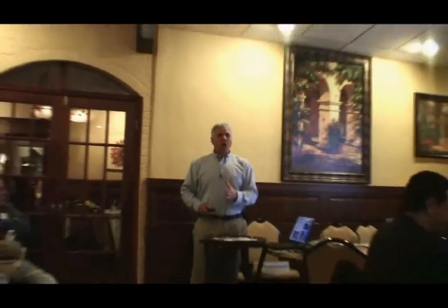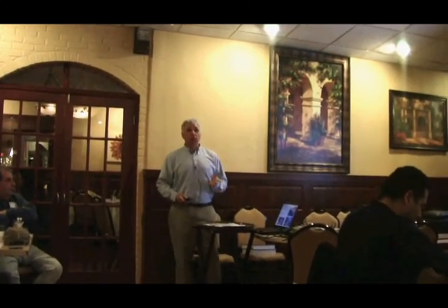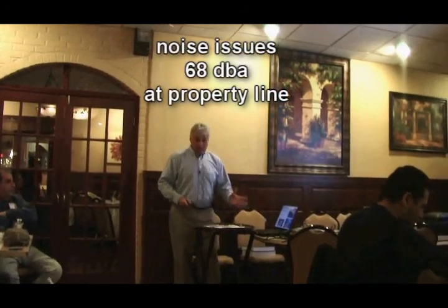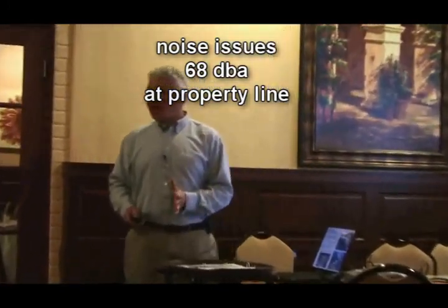Yes? Anything like a property line, like the fence? When I say there's a fence, do you have to be a certain distance from the fence or anything like that? The code right now, the village code, is property line, not fence. But it is more an issue of noise. Most villages accept the generator set at 68 dBA at the property line. So you can be at the property line as long as it's 68 dBA. Now that becomes a function of the village inspector, but that seems to be what's acceptable. That is our push when we do presentations to the village inspectors.